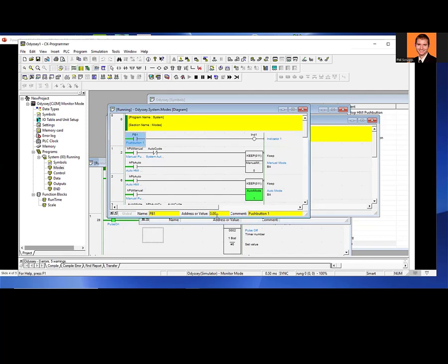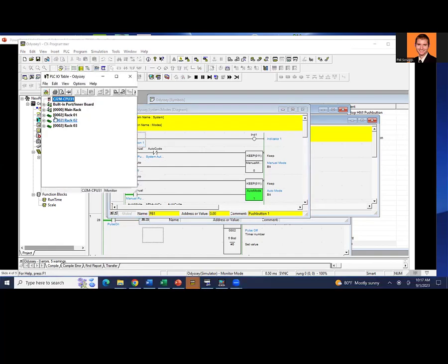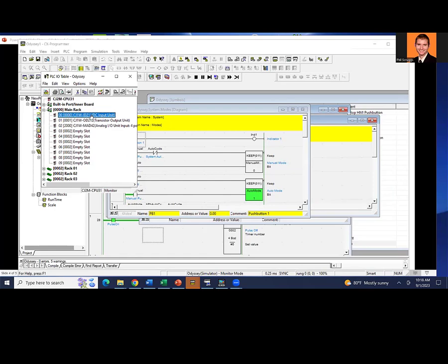So if I go up here back to the push button's address is 0. That area is called the CIO area, and all the lower numbers of it are assigned to physical I/O. And that's not an obvious thing here, but when I put my first card in here in the I/O table, let's see how that looks. Go ahead and open that up. And I put an input card in here. It landed at 0. So that is a physical address, CIO area 0. And so if I just type in a number 0.0, I am getting the first input point of that input card. That's a little confusing because there's not an I or an O or a Q or an X or a Y, which sometimes people use to designate that that's IO. It's just a number. So when I go in here and I put 0.00, that's what I'm pointing at as the first push button here.